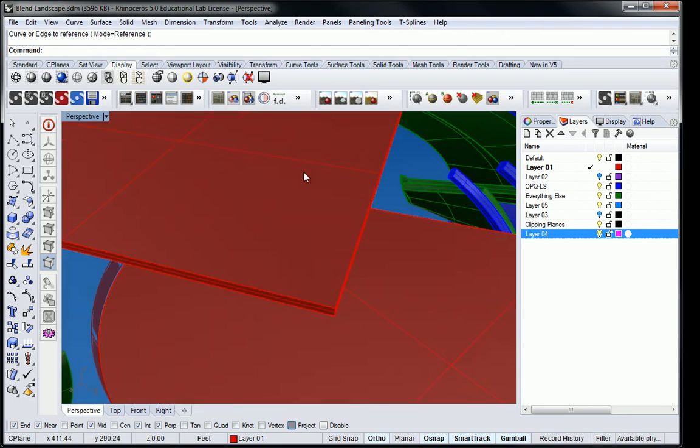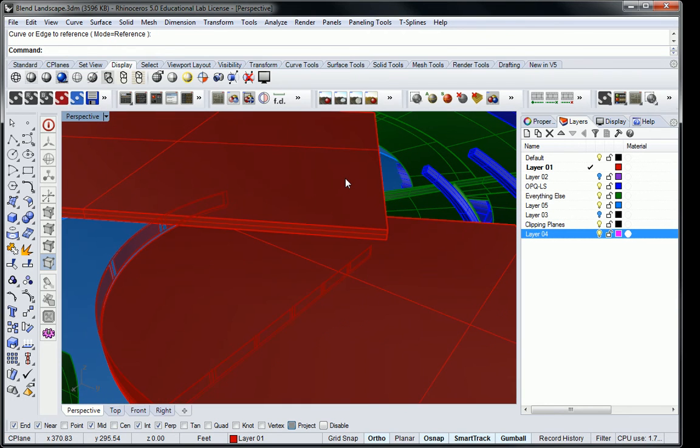But what you should know is that on any stair, the rise and the run, so that would be your riser height and your tread depth, is what's going to determine the slope of the stair. So schematically, we're going to show it at a tread depth of 11 inches from nose to nose and a rise of 7 inches. That's kind of a ballpark number.